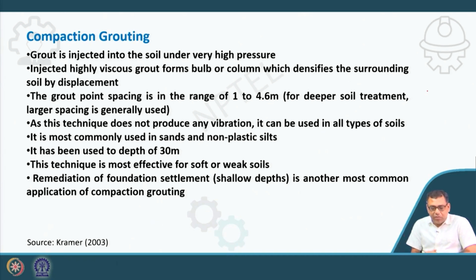Clear? The grout point spacing is in the range of 1 to 4.6 meters. Here also it is done in a grid pattern. The spacing is 1 to 4.6 meters. For deeper soil treatment, larger spacing is generally used.